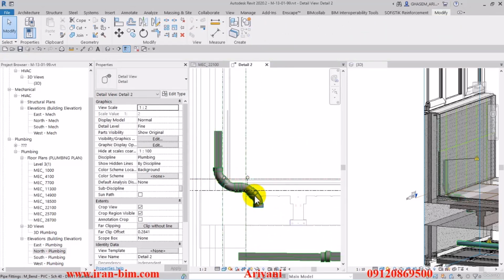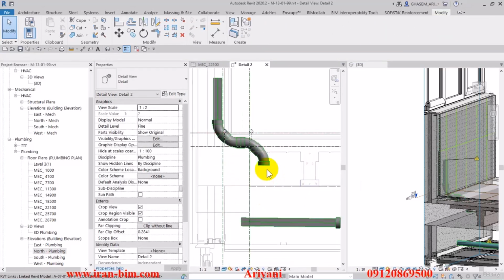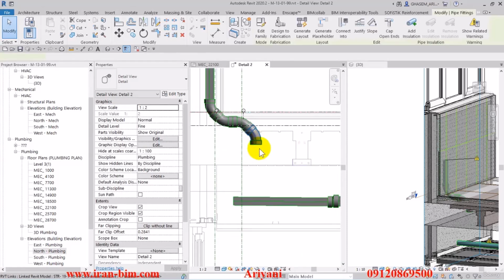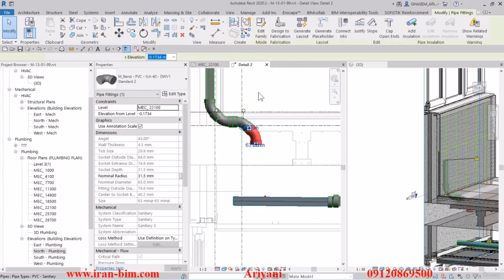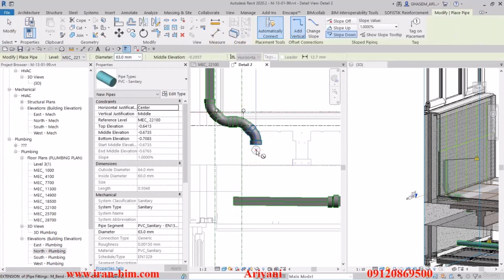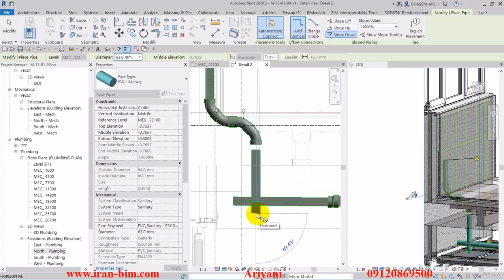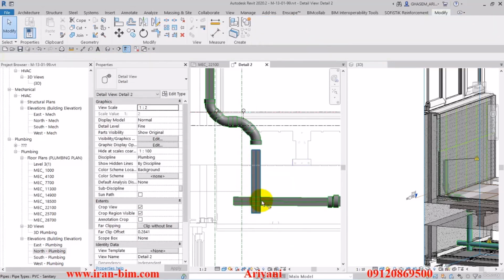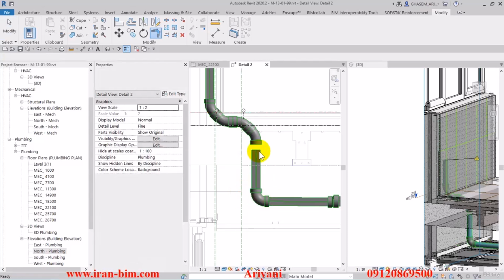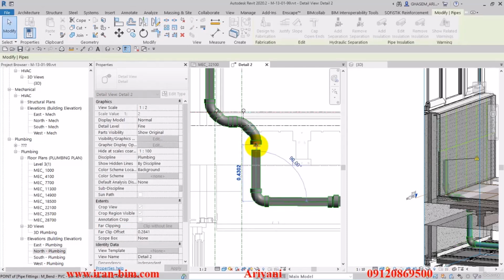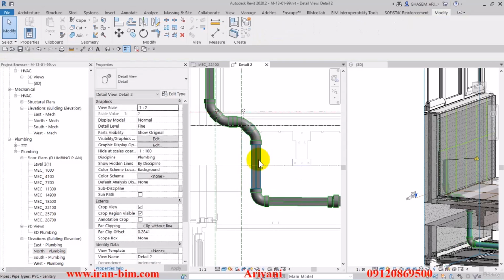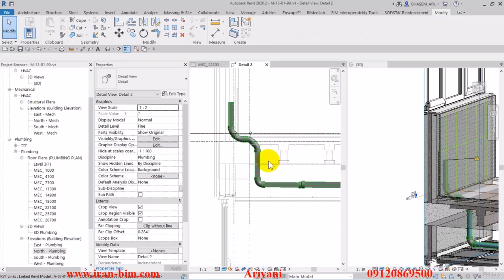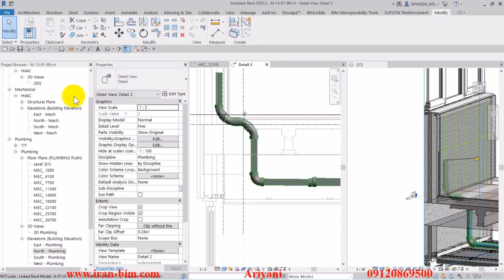And then once again, to be sure, we connect it up like this. Alright, so it's all fine up to this point. But then we'll have to select the pipe that we have here. And then using the create similar option, we'll continue drawing a pipe all the way down here. And then using trim, we'll connect it up to the pipe that we have on the bottom. And then I'll connect the newly created piece to the pipe system above.